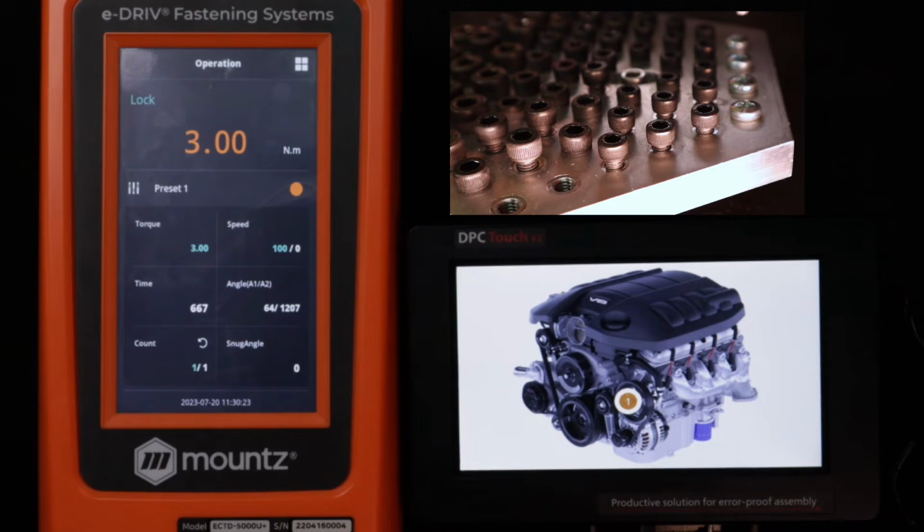Now, the way we have this particular program set up is that these 3 fasteners here will be a 2-pass type of assembly. We are just going to run the first pass down 500 degrees of rotation. So we're just turning that fastener 500 degrees. 1 revolution is 360 degrees, so we're going to go a little bit less than 2.